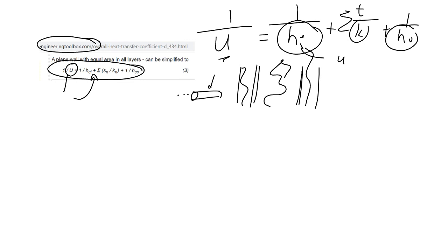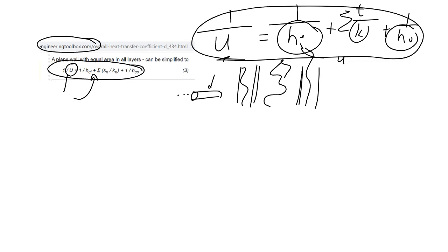And when you do your ultimate design and you have to incorporate a heat exchanger, I suggest you start with typical U values, until you have fine-tuned your design to a point where you say, okay, this is now the area that I have chosen, and based on this area, I can now calculate the internal and external heat transfer coefficients, h in and h out, using my Prandtl number. Study.